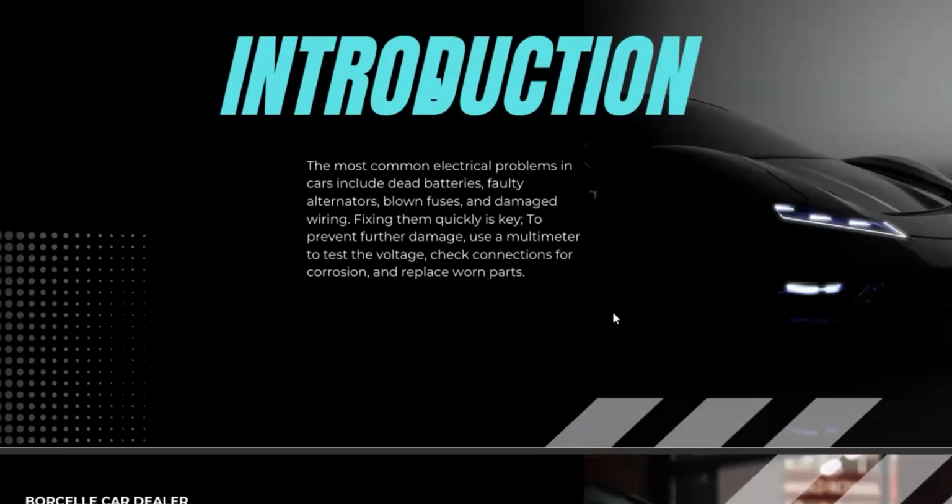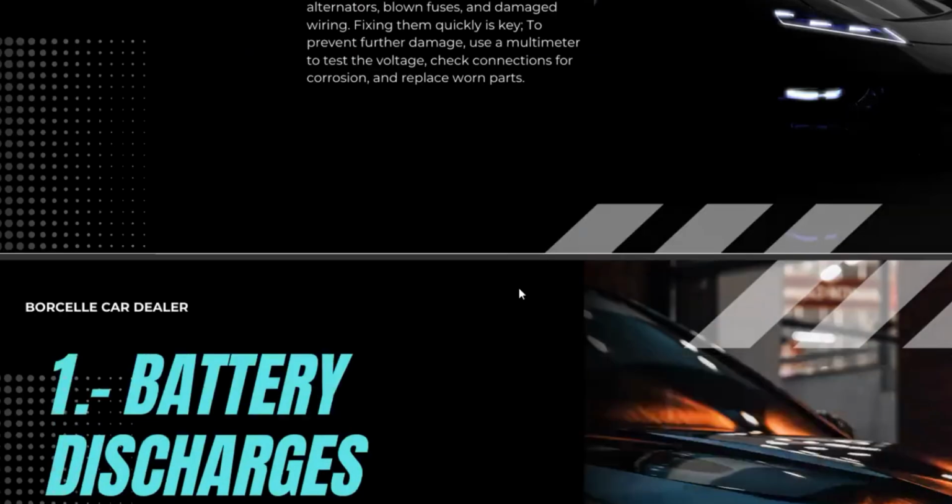Introduction. The most common electrical problems in a car include battery faults, alternator failure, blown fuses, and damaged wiring. Fixing them quickly helps prevent further damage. Use a multimeter to check the voltage, check connections for corrosion, and replace the faulty part.